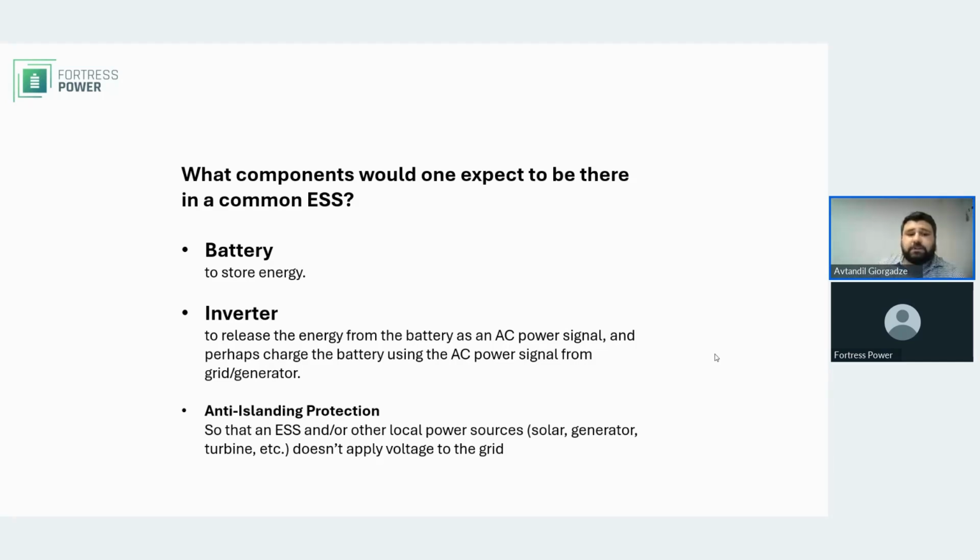One function is to take battery DC, turn it into AC, and send it to the grid, or send it to the circuits in your home. And the other function would be to take the AC from the generator or from the grid, turn that into DC to charge your batteries, if, for example, PV is not available or something of that sort.